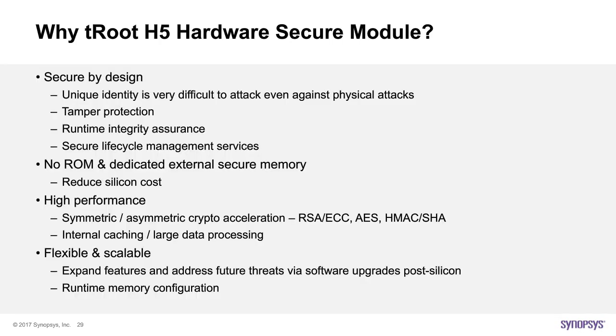So why tRoot Hardware Secure module? Well, first, it's secure by design. It offers the protection of the identity that is very difficult to attack. It provides strong tamper protection. It performs runtime integrity assurance. It has a secure key programming to external port, which makes it ideal for packet processing features, for example, like a TLS application. And it offers functions that can perform an overall security lifecycle management service for your system.